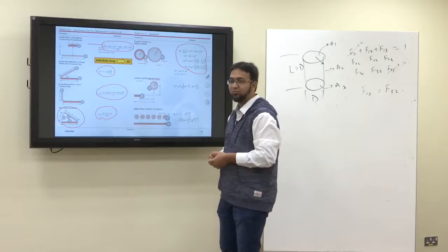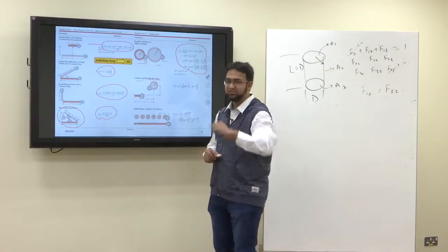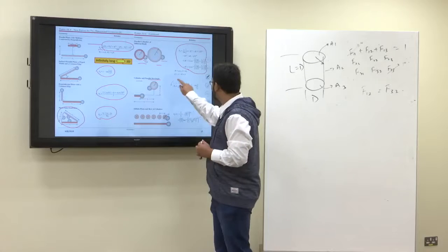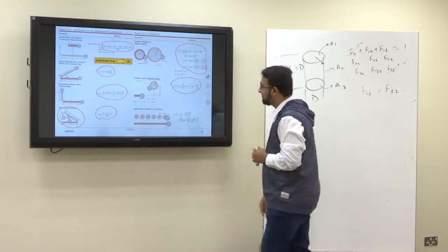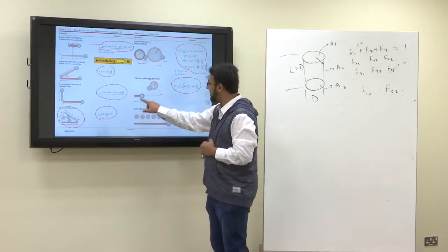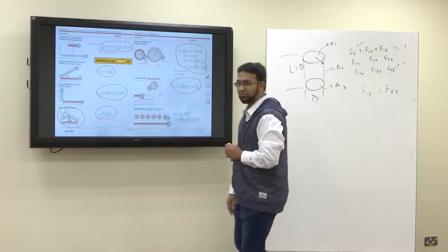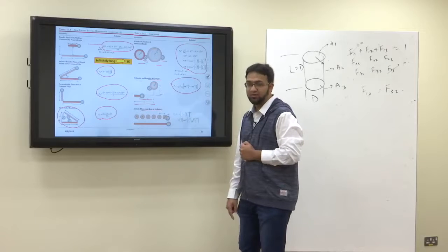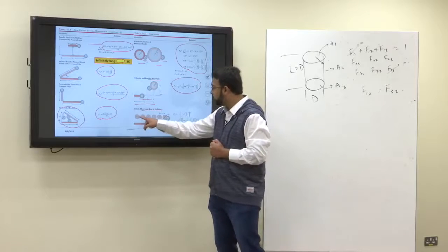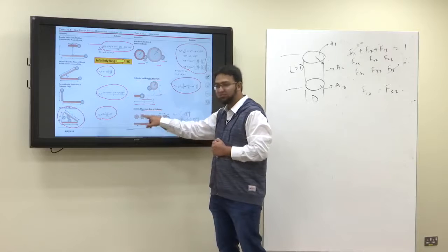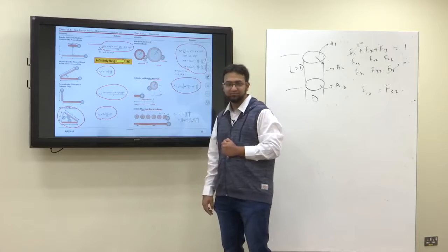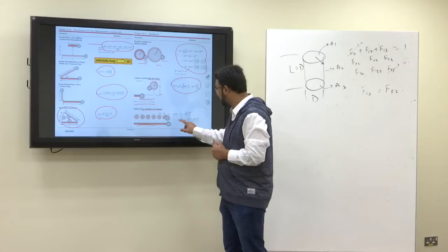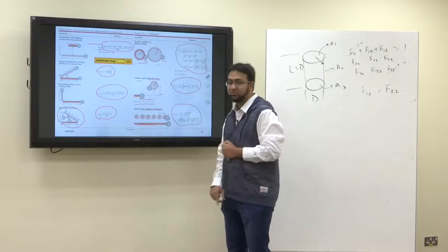So what's the view factor between a plate and the cylinder? Where plate is i and cylinder is j, the view factor is given by this formula, given these distances known, L, S2, S1. If I have an infinite plane and a row of cylinders, let's say this is a shell and tube heat exchanger where this is your shell and these are the tubes, then the radiation exchange from the shell to the tubes will be based upon this view factor.